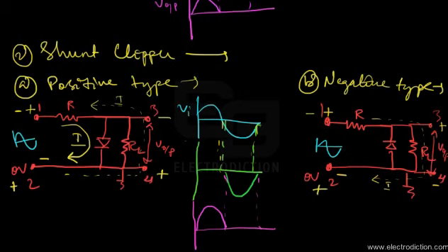So in that case, here the diode is forward biased and a huge amount of current flows through the diode, and as a result, the diode, just being forward biased, behaves as a short circuit element, with the result that across RL the output voltage just drops to 0. So in this case we have no output voltage in the second half cycle of the input signal.